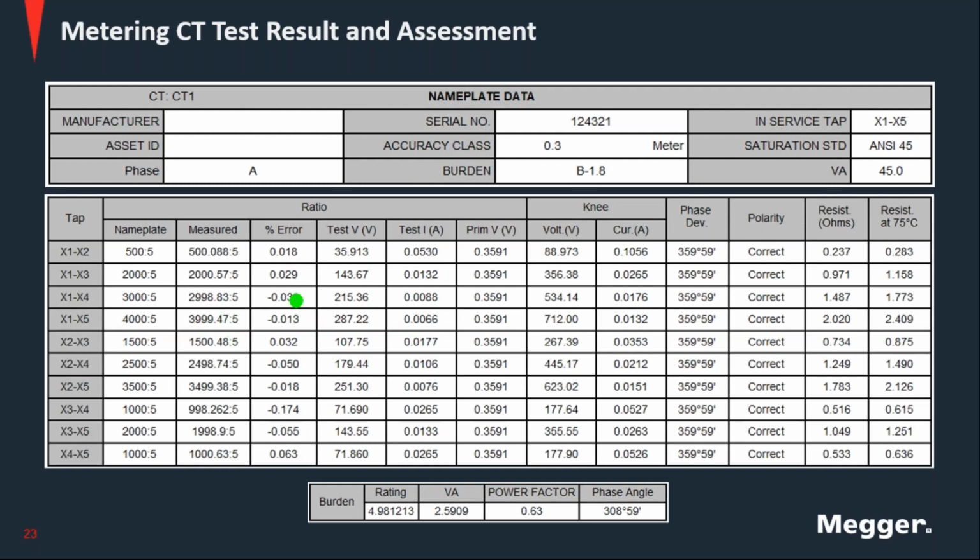So that means that there's an error of 0.013. According to this accuracy class, we could have plus or minus 0.3% here, which we are far from, meaning that the ratio is very good. And we can start picturing this in a parallelogram, and we know that it's going to be pretty much in the center of that parallelogram, at least in what relates to the y-axis.